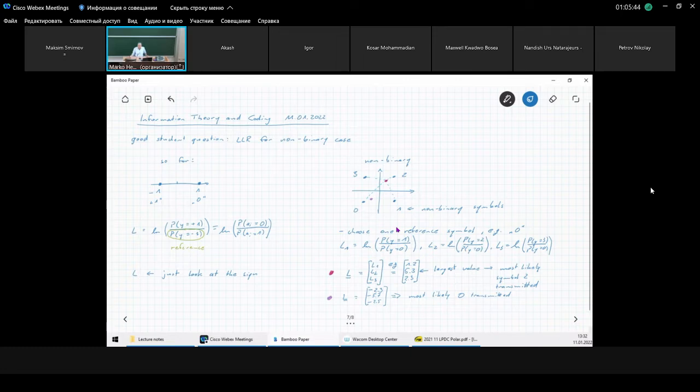Depending on what we do with these log likelihood ratios, we might be able to get a benefit from this. If we have a very large value, we can say we are very safe that it is a 0. If we have three fairly small values, as would be the case if we were somewhere around the 0, then these values would all be in the same range. Then we could conclude, well, it is a 0, but it's an unsafe 0. So the values also give us some information on the reliability of the estimate.